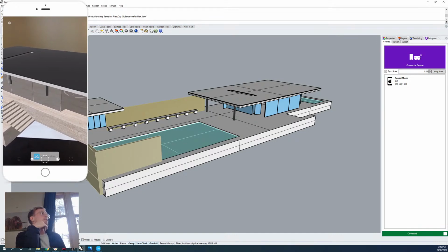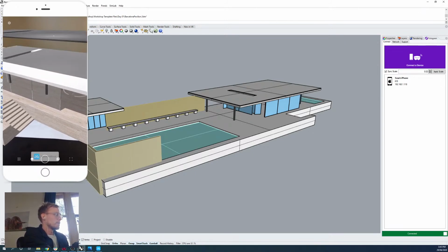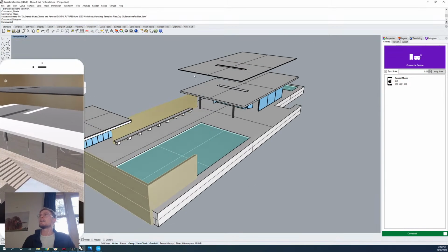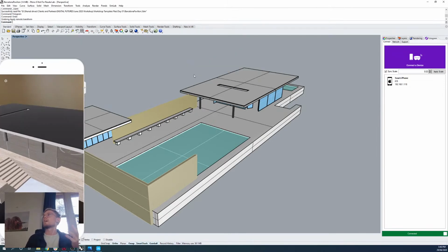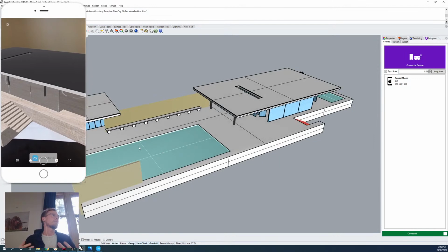One thing I will touch on just really quickly, if I move something like we were doing previously, say I move that roof on top of the screen, I can just go over to Rhino and go undo, and then undo that. So whilst you can't undo a command inside of the Fologram application itself, you can easily undo a command in Rhino if you accidentally do something. So we're creating a live connection between these two things.